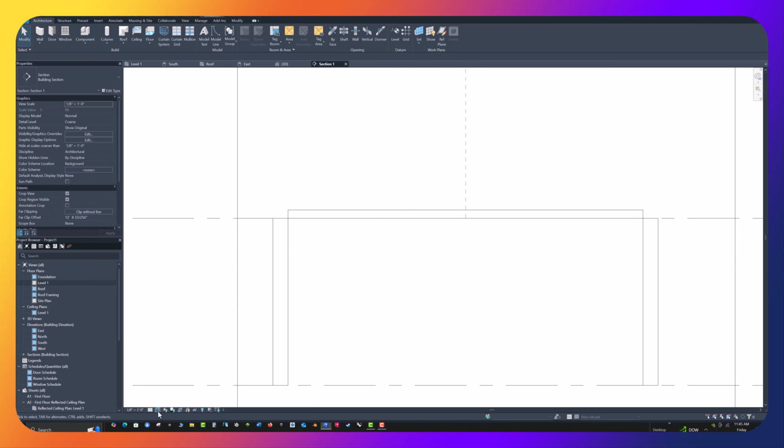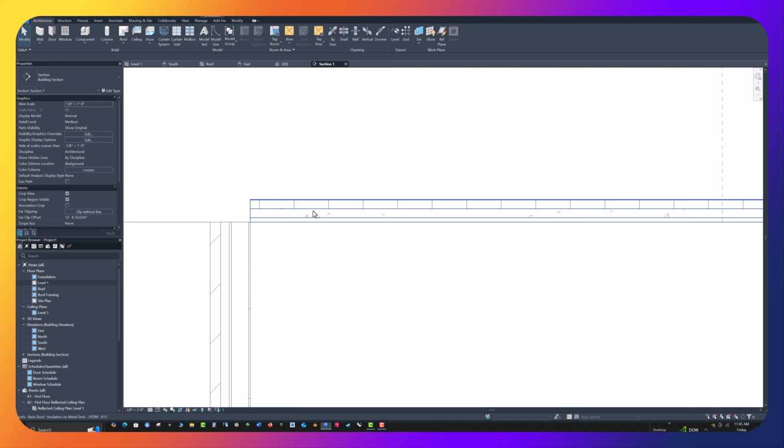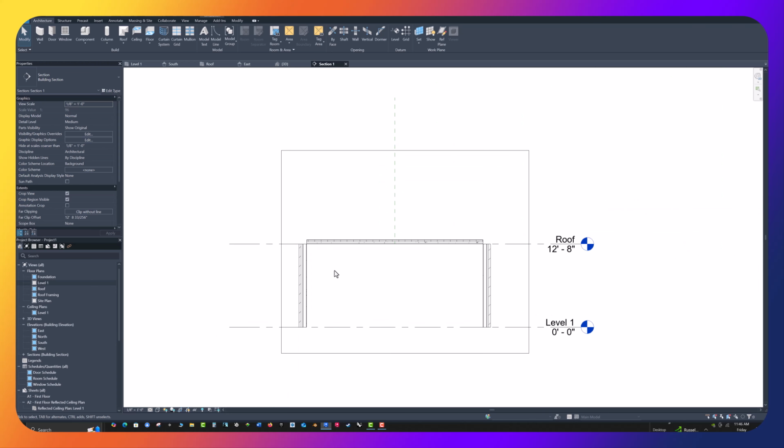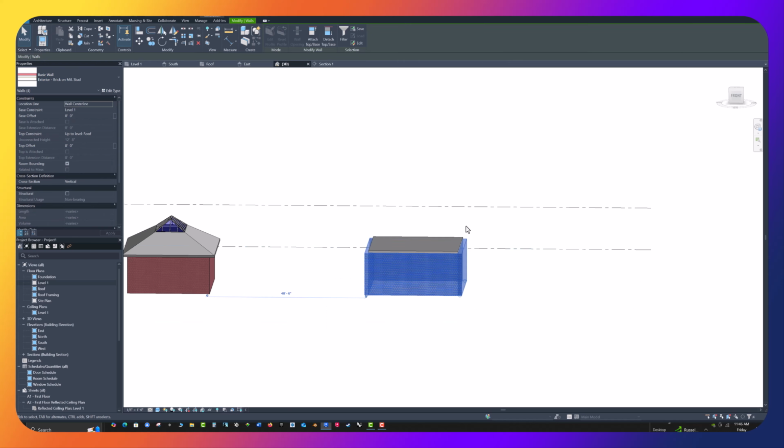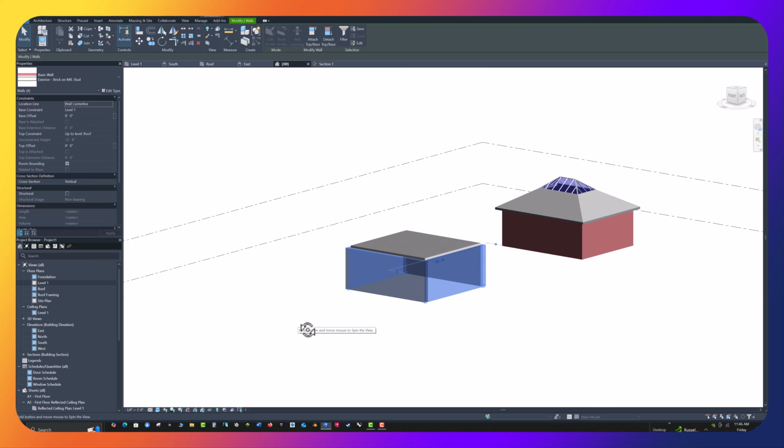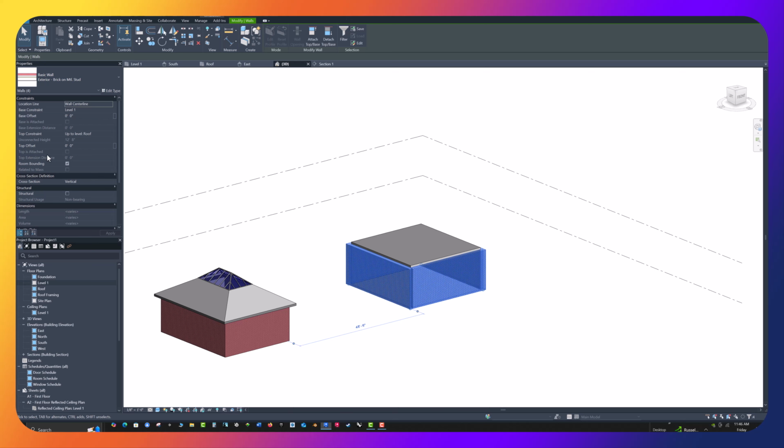Now here's my roof. Insulation and concrete, and then metal decking. Now we want to put a parapet around this, so I'm going to go to my 3D view, and I'm going to select all these walls. Make sure I got them all. I do. And I'm going to give the top offset, say 3 feet, and apply. And now I've got a parapet.